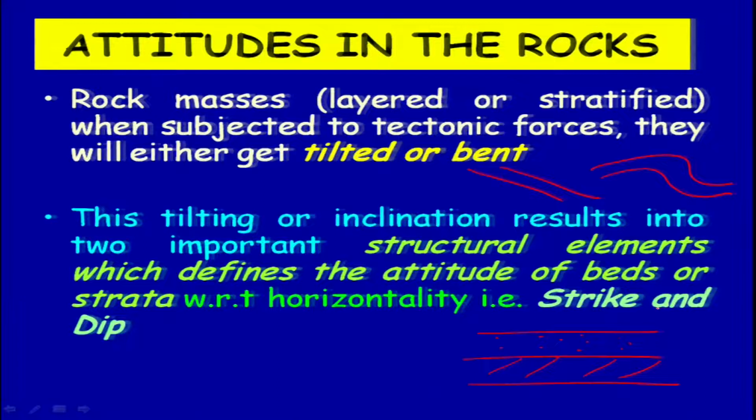So we will quickly look at what strike and dip are, and then move ahead in the course. Now, you will be able to see this only if you are looking at a section, but based on the photographic interpretation, you can also judge what type of feature or landform you are looking at. That is the important part. Without understanding the attitude of rocks, you will not be able to go ahead, because the final interpretation of the map you are going to prepare will require this information.